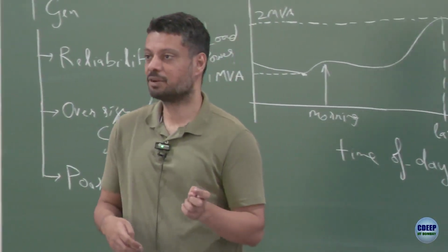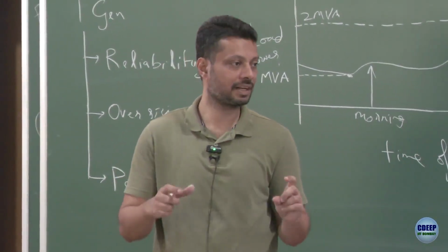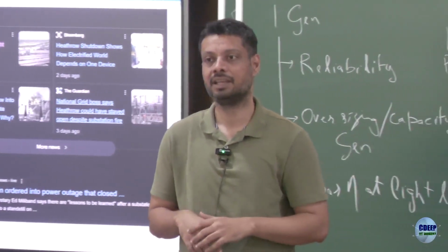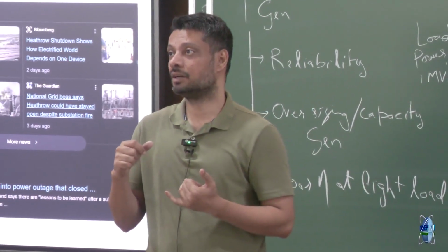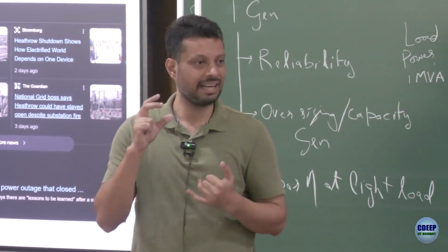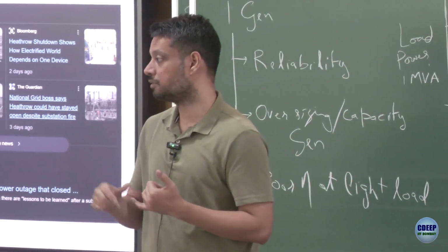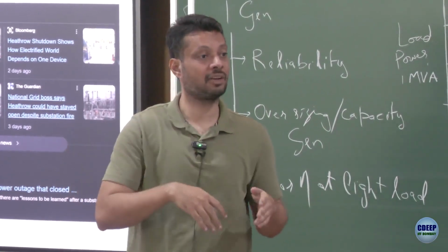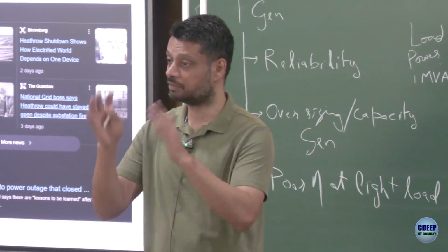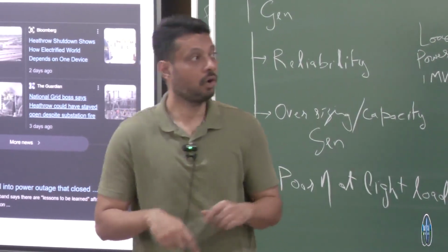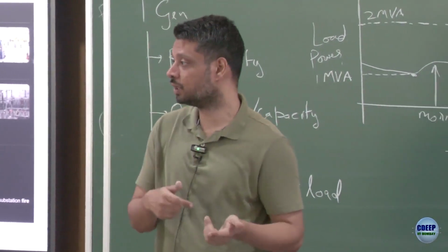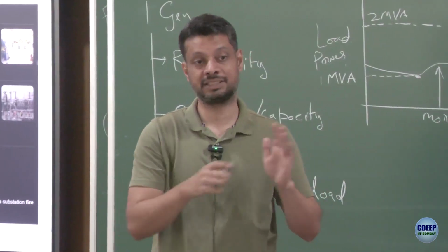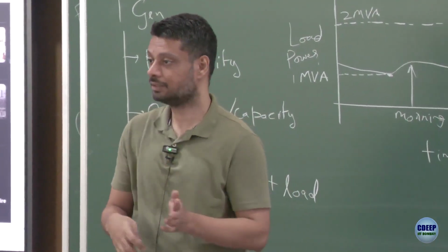The important thing which comes out from this event is that this transformer, which of course we study and which appears to be a very robust and simple thing, is relatively custom manufactured, especially the big ones, and it may take substantial time. If you place an order, it may take something like 6 months to a year to manufacture that transformer. With all the renewables, all the solar, a lot of solar panels and power electronics are required, but this transformer is required in each and every place.